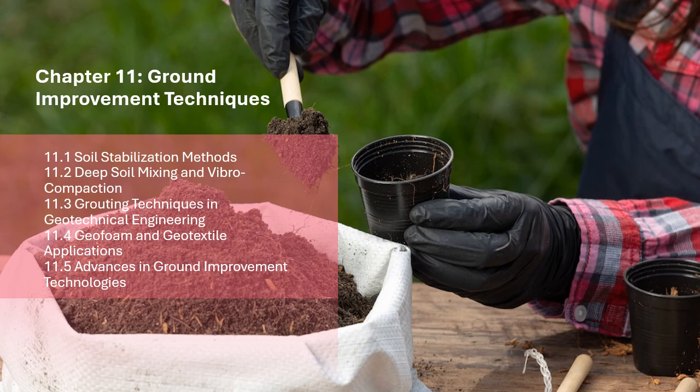1.3.3.1 Foundation Improvement. Grouting can be used to enhance the load-bearing capacity and reduce the settlement of foundations. It is commonly used for the improvement of weak or unstable soils beneath existing or proposed foundations. Grouting methods such as permeation or compaction grouting help increase soil strength, reduce settlement, and prevent structural damage.